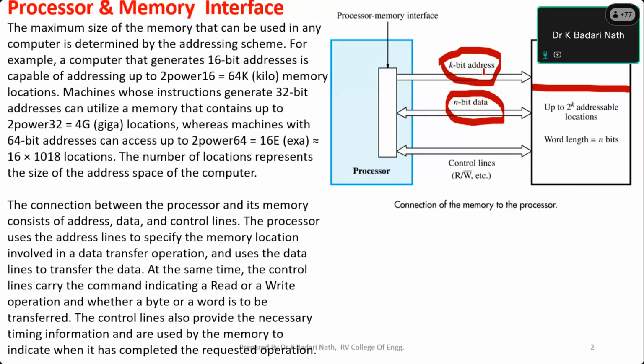Now, as soon as we put the address and the data, does the memory know that we have placed the data? No, the memory does not know, because even if you have not placed any data, some data will always be there on the data bus, either all zeros or all ones. That does not guarantee that valid data and a valid address are always there. Memory does not know when you place a new address or new data. So the processor has to inform the memory, after placing the address and the data, that it can now start writing the data into the memory.